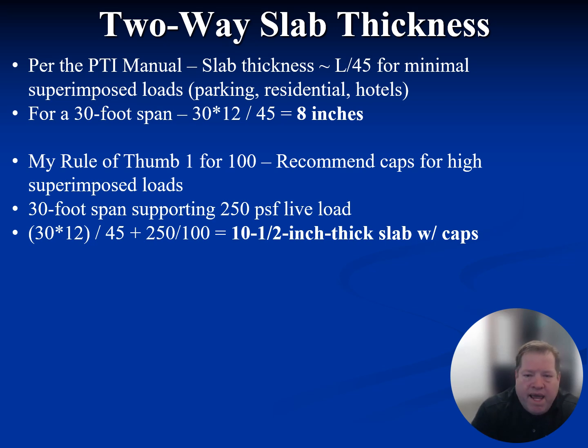One of the things I'm going to hammer home a few times, and this will hopefully save you if it comes to that: the cap thickness and its plan area have a very strong impact on the slab thickness. So if you design or budget a slab with caps, and let's say in this case it's 10.5 inches, and someone, the architect or someone in your firm, says we don't want caps, we're going to use stud rails for punching, that's fine.